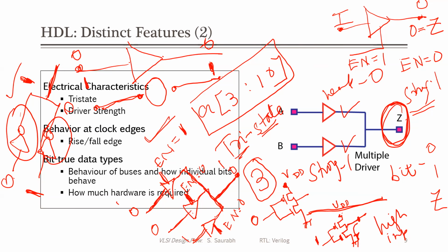So this PMOS will be connected to VDD and you will have a low resistance path through this. Now, if I connect this to this, you have got a low resistance path from VDD to the ground, and that's why you will have a short circuit, right?